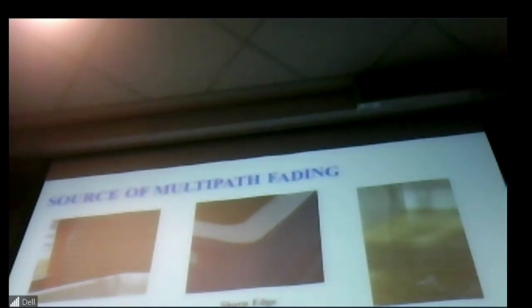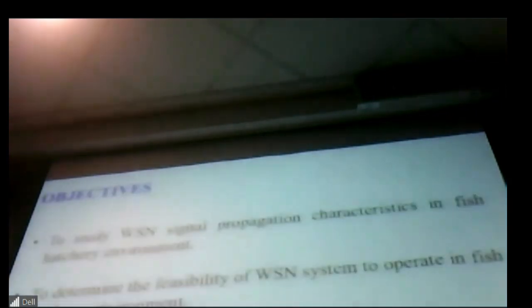We see a potential for multipath fading, which can increase the packet error rate. There can be sources of reflection, such as sharp edges, sources of refraction, and also water pipes. A water pipe is just a small thing, yes, but we have 30, and 30 of them are a source of scattering.